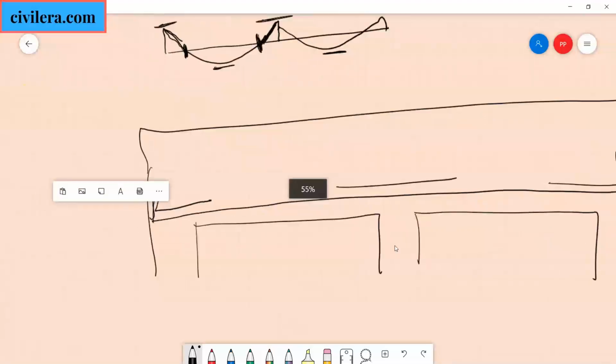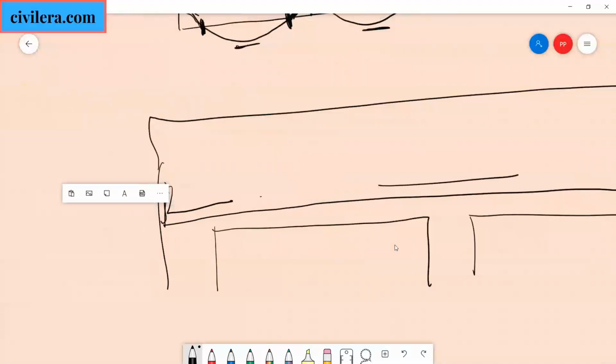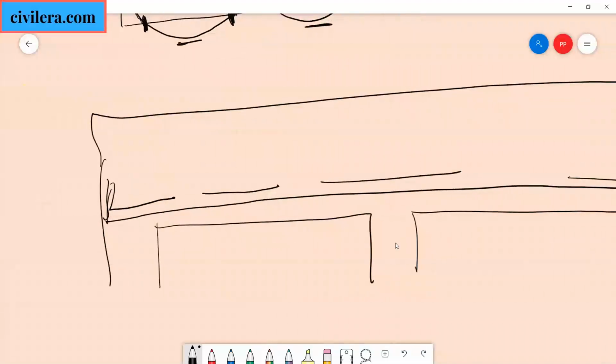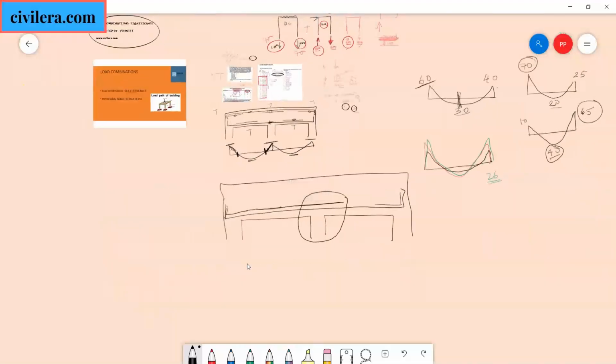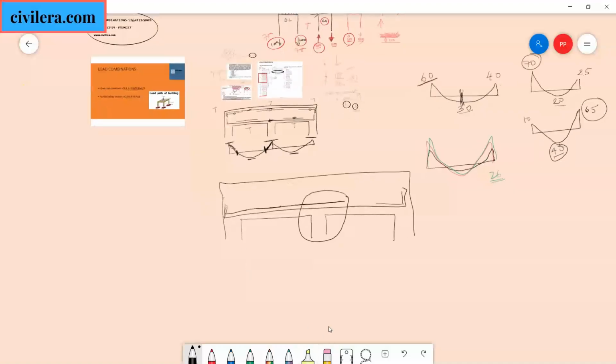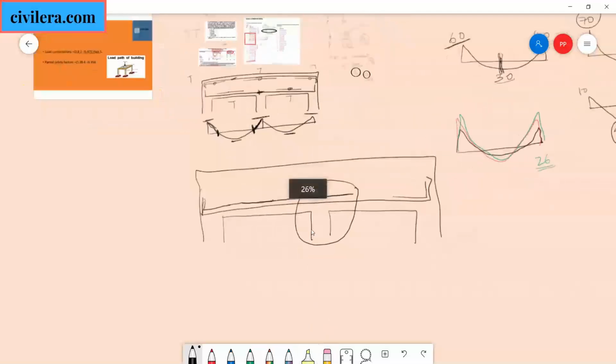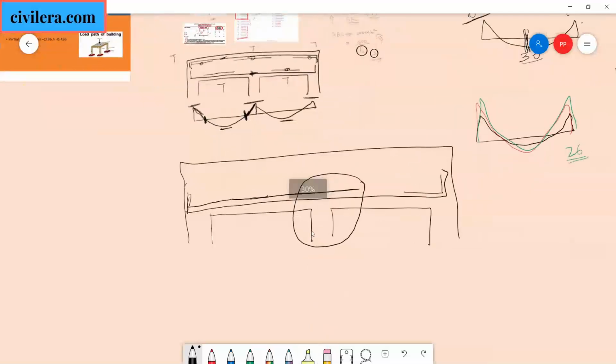Many times you can detail it out. Many times what happens is you already have more force here also, and more force here also. In that case, you might give a single extra bar like that. That's a different thing altogether. But the point to note is that there is a good chance that you can have more steel in the support. And in real projects you can check that this kind of behavior will be more prominent for very short beams than long beams, say where the spans are less.